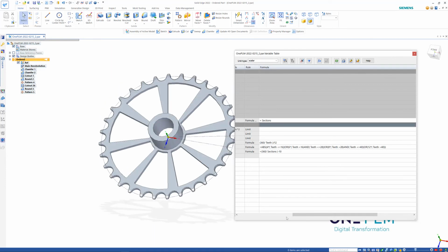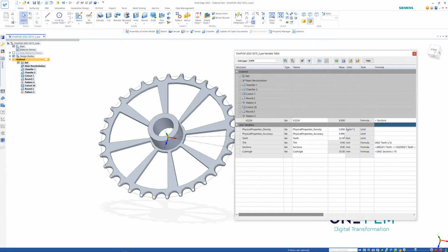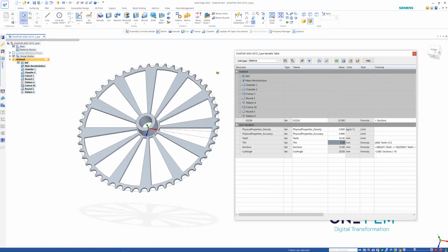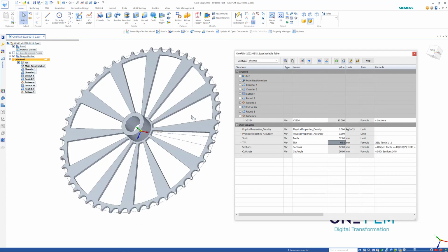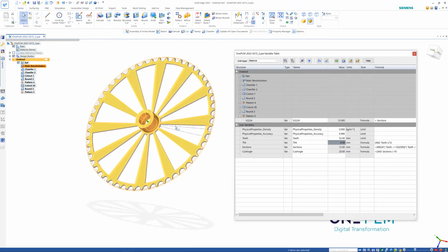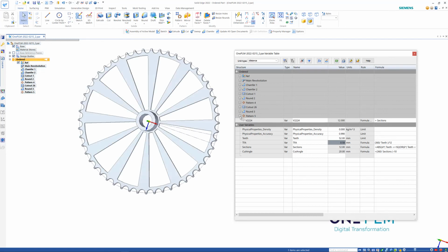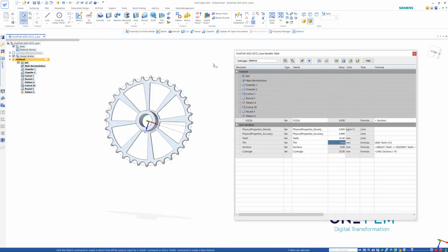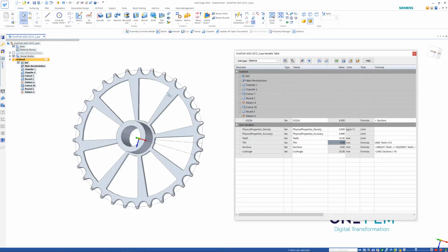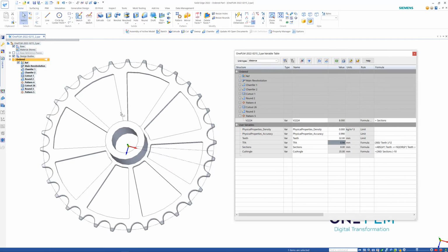And let's just do some checking on there, see how that looks with the different options. Let's go to 52. See how that rebuilds. Might look nicer if we do a parallel, so we might have to go and change that cutout sketch slightly. Let's go and change that back to 32.